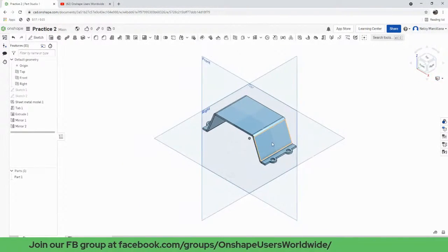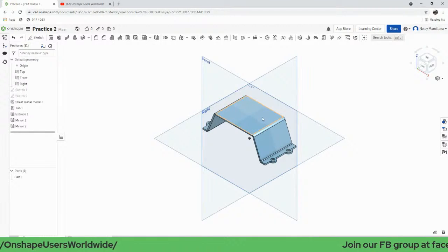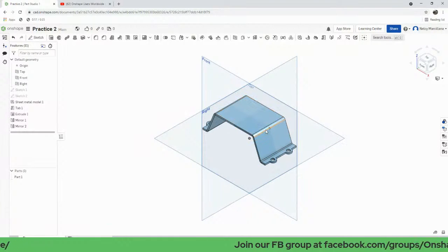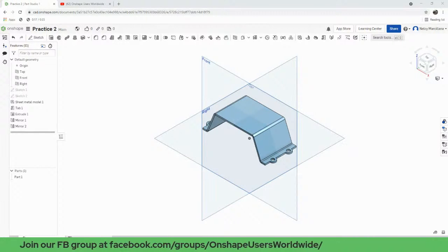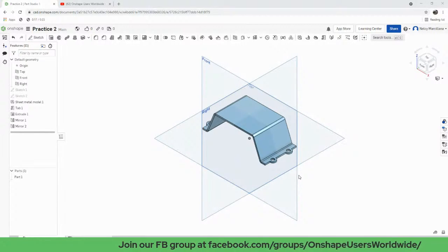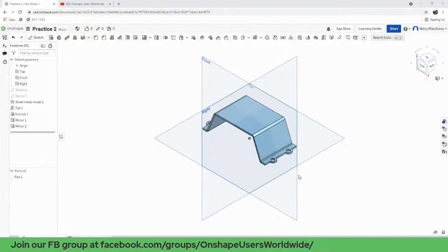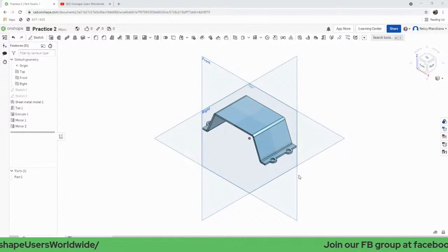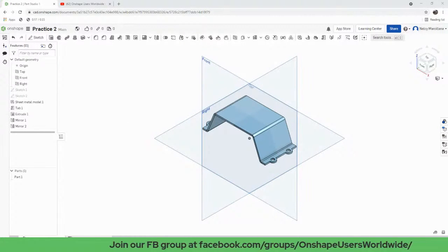Okay. So our next intent is to create or cut material here. So to do that properly, let's head over to Sheetmetal table and flat view. This functionality is currently available only in Onshape's browser platform. So edit an existing sheet metal model's bend, rips, and joints. And also view the sheet metal flat pattern.